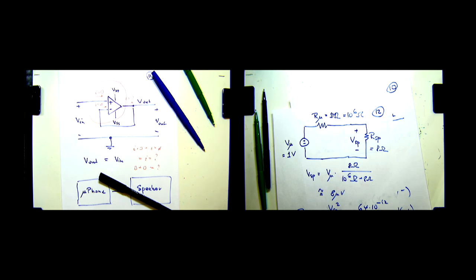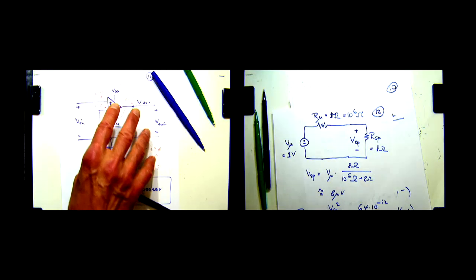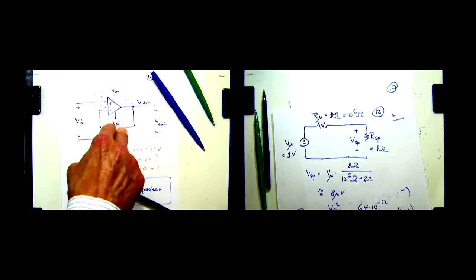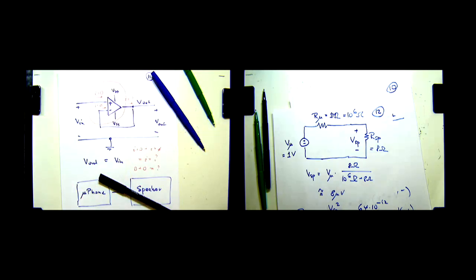You draw the circuit diagram, it's got no supplies. Then you go to the lab and you don't hook up the supplies, and then nothing is going to work, I guarantee. Okay? So don't forget, you need to connect them to voltage sources. Showing these supplies in the circuit diagram makes it just about unreadable. So we never show them, but in the lab we put them there.